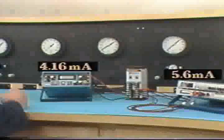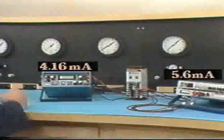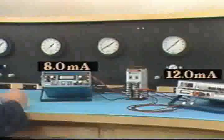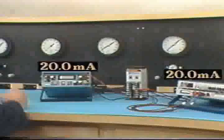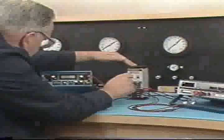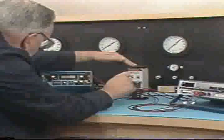The values displayed by these milliammeters indicate that the first zero has been properly adjusted, and these values show that the other zero is properly adjusted. When the input and output both display 20 milliamps, the span adjustment is correct for this instrument. Check the other two values after the zero and span adjustments are correct. Then make any other necessary readjustments.